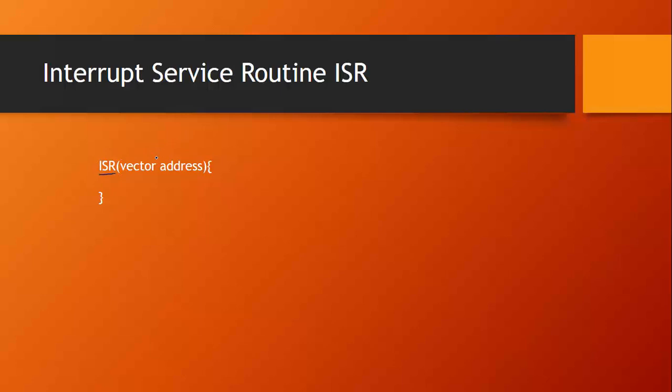These vectors correspond with the vector table that I showed you in the beginning, but here we refer to them by names. We use a symbolic format to address them. We don't use addresses like 0x09 per se. I'll show you exactly how to know the correct name to use for the associated interrupts and where to find that inside the header file that we've included.